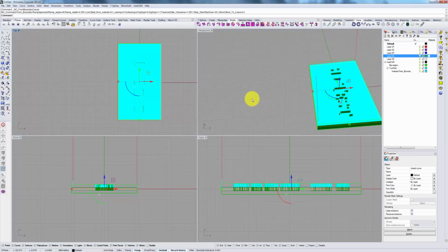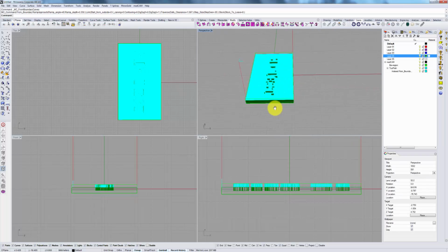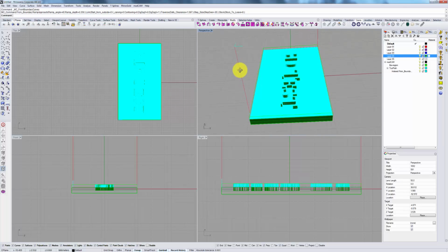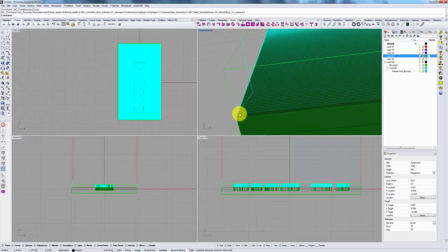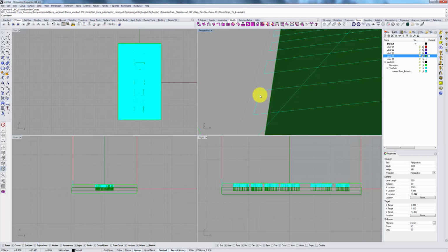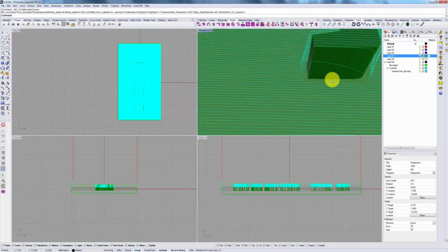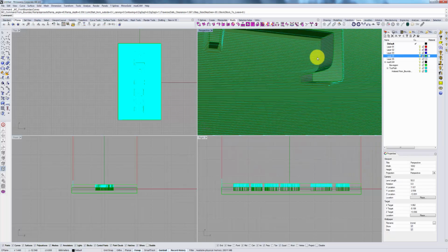And here we are. So the toolpathing calculation finished, and once again we see a similar picture with our starting point, the entry point if you will, indicated by this right angle blue thing, the descent, and then the beginning of a toolpath. Every bit pass is marked with a line. The connections, as you can see, are these squares, and you can see that as it approaches, it starts to pick up and cut around this extruded area.